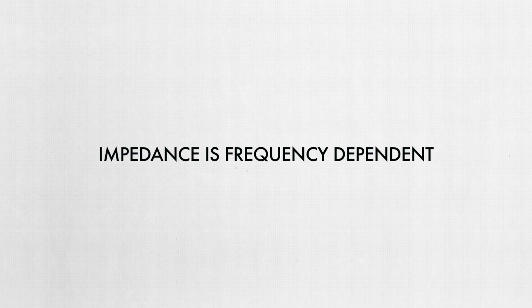While the specs I've shown you in this video state only one number for the input impedance or output impedance of the devices, that is actually just the impedance at a particular frequency, say 1 kilohertz. In reality, the impedance of any circuit will vary throughout the frequency spectrum. That means the impedance at 100 hertz is likely not the same as the impedance at 1 kilohertz, which is likely not the same as the impedance at 10 kilohertz, and so on.